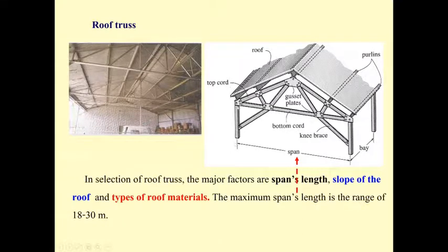We build a column, and then after building the column, we build the truss, and we use the crane to lift the truss up. Okay, and most of the trusses have the gusset plate at the connection to make the joint strong and with stability. And then we put the purlin link between the trusses, and then we put the metal sheet on the top.